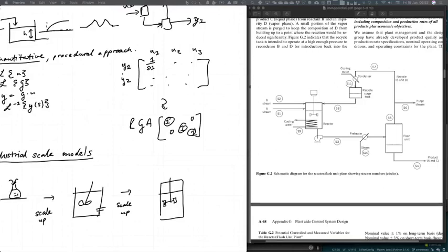But that's kind of what you're asked to do, is to say, well, if I were to change the cooling water flow rate, how much would that affect the condensate, right? Going from full open to full closed, how much less condensate will form? This surge tank level, how high does that level get? What's the effect of the level on the flow that goes out, approximately, order of magnitude, right? Many of those things you can estimate.